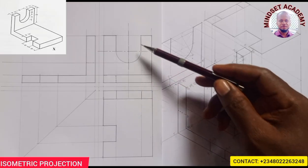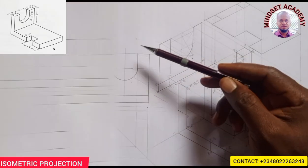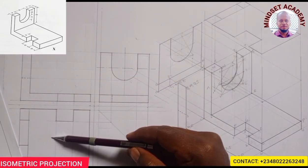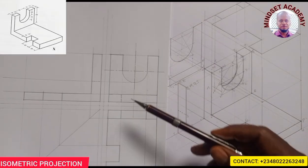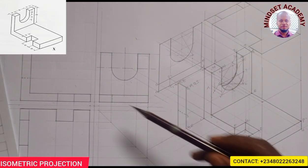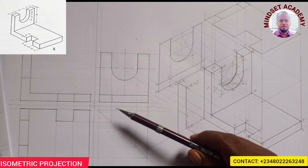So the one at the center is always the front elevation. You see this at the center, front elevation. You see this at the center, front elevation. While the plan is always under the front elevation. Looking from this side, this is what we'll get, our front elevation, plan, and end view. But looking from this side, this is what we get, our front elevation, plan, and end view. So this is in first angle projection.